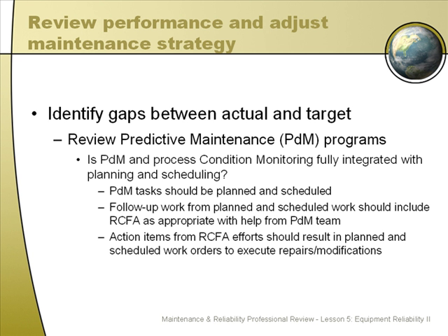Here's a good question. Is the predictive maintenance and process condition monitoring program fully integrated with planning and scheduling? In a lot of cases, organizations will build their predictive maintenance and condition monitoring program separately from everything else in their maintenance operation. And this little group will work autonomously away from everyone else, identifying problems and generating work orders or some other kind of exception report to tell the maintenance department that action needs to be taken. I would highly recommend that you integrate these groups directly into your planning and scheduling group.